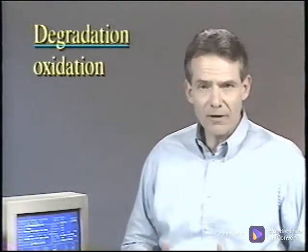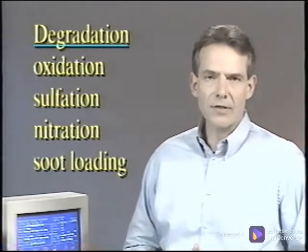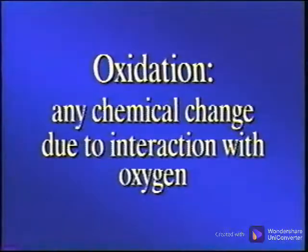Maintaining lube quality is a key to ensure consistent, smooth-running machinery. Degradation removes the lubrication properties and may destroy some of the additives. The primary sources of oil degradation are oxidation, sulfation, nitration, and soot loading in diesel engine applications. These all increase acidity and deplete additives.